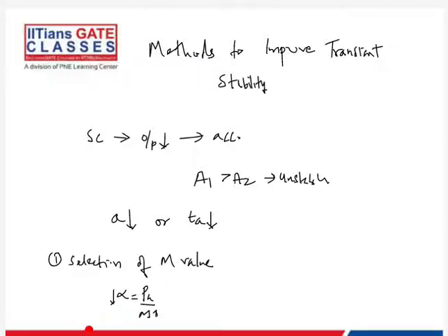For the sake of transient stability, we prefer to install larger capacity generators. But again, this has a big issue with swinging together, and if one generator goes out, what happens? So in terms of system design, we usually tend to have smaller generators, but this is one approach.